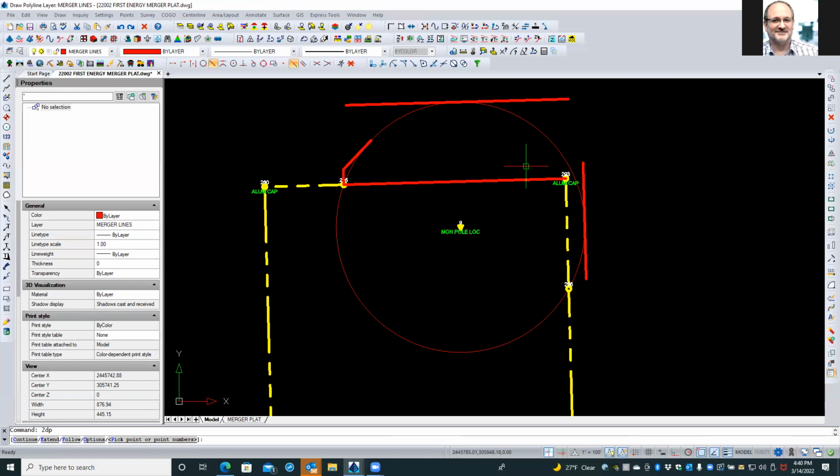All right, so now you're going to draw from the end point, that one that we just established, just northeast of that, right there, click. And you're going to snap to the tangent of the circle, so either from the toolbar or shift right click. Where's the toolbar that says tangent? Right there. Click, and that's just for this one pick. Click, hit enter, and you're done.